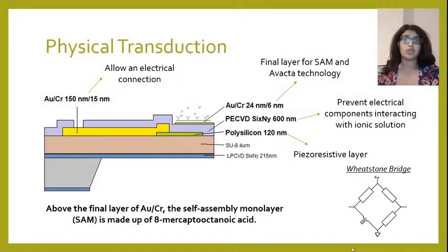The final part is a smaller layer of gold and chromium where the SAM, made up of 8-mercaptooctanoic acid, and the Avacta technology is deposited. To process the generated signal, we'll be using a Wheatstone bridge and an amplifier into the microcontrollers to calculate the concentration.